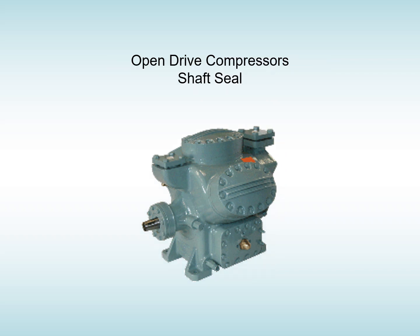Quite a common job on an open drive compressor would be the shaft seal. The shaft seal's there to keep the refrigerant in the system but still allow the shaft to turn. There you can see the shaft seal inside there.